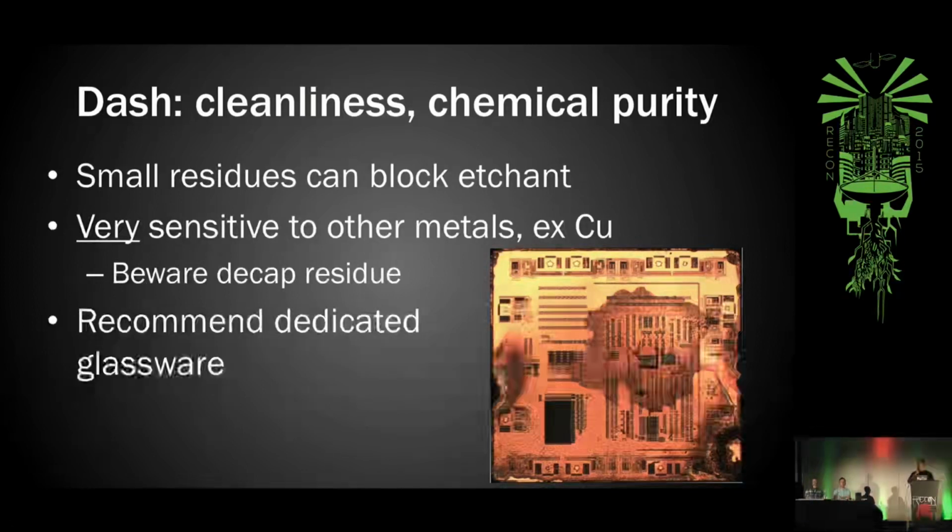Another issue I found was I was using the same beakers for doing the decapping as for the hydrofluoric acid etching. And the problem is that nitric acid will react with copper very readily, which is present as the lead frame in a lot of these chips. And what this does is it creates this copper nitrate, which then interacts with the hydrofluoric acid to cause a lot of side reactions that will kind of copper plate the die and basically stop this reaction altogether. So use dedicated glassware, and things started working a lot better.